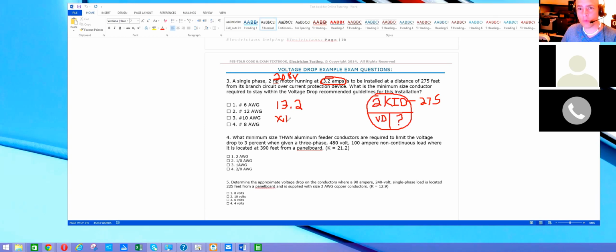So 13.2 amps is going to be times 1.25, and you can find a couple of references to that in 430, 430.22 being the controlling one. But this math is really what I'm putting in for this I, because my demand on that wire is a little bit more than 13.2 at the end of 3 hours, so it's probably 16 and a half.